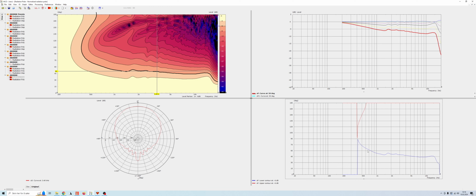In this case, it's quite smoothly going towards about a 45 degree, which is 90 degrees beam width at the top end, and it slowly expands towards the lower frequencies. At 1 kilohertz, it's about, I would say, 105 to 110 maybe degrees beam width, and then it widens as you go lower.